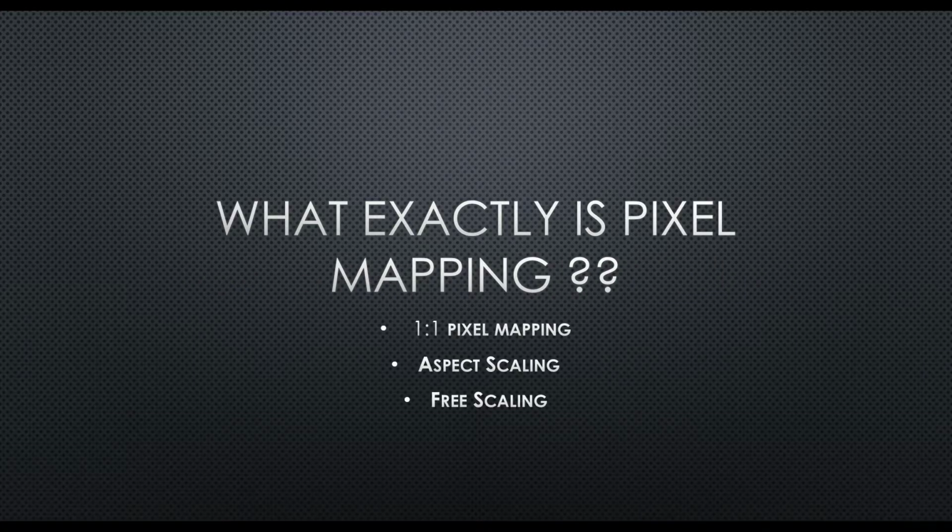So when we're looking at pixel mapping, let's focus on that first. It's going to be a one-to-one pixel map. If your LED screen is, let's say, 1920 pixels wide by 1080 pixels tall, and you're supplying a 1920 by 1080 signal, then it will be pixel mapped. If you are altering that resolution, let's say your input resolution is 1280 by 720 and your LED screen is still 1920 by 1080, you are going to have to scale that.